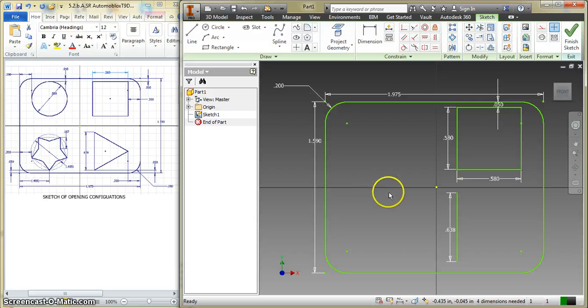So let's first make sure this line is lined up exactly where I want, and then my other 2 lines will form where they need to go once my line is set. So I can dimension, I know from the bottom to this point, so you can see that I get this white dot at the end. I want from there to there to be 0.05. So I know that's all set.